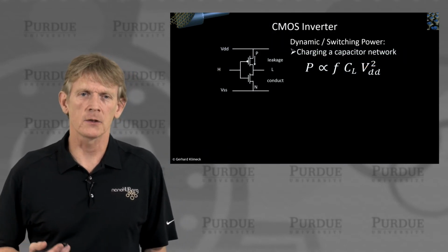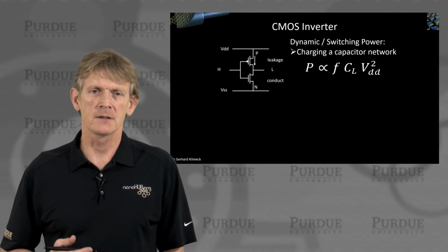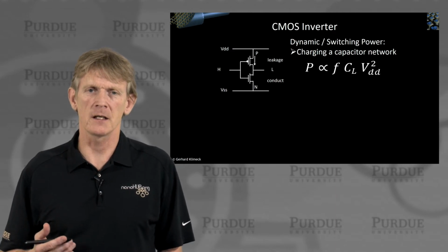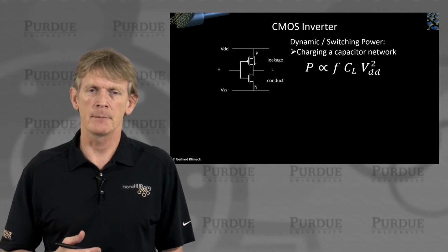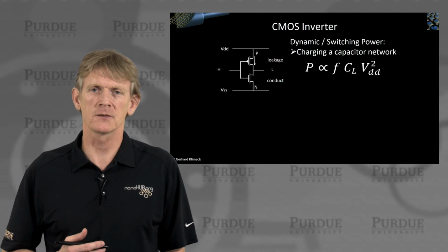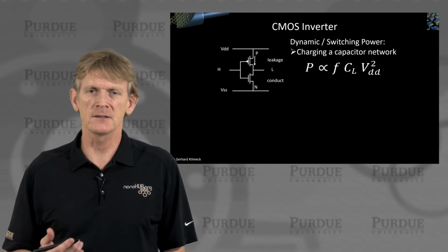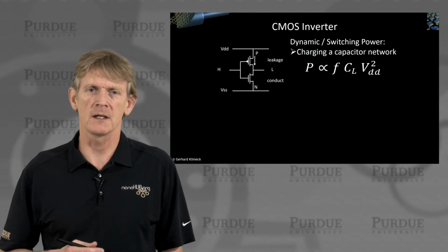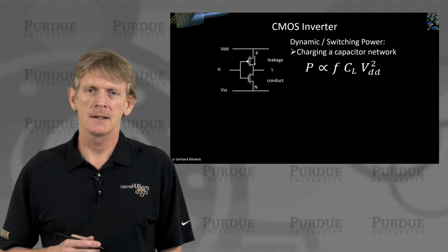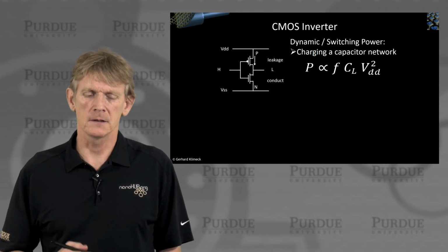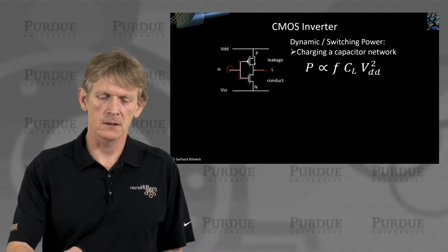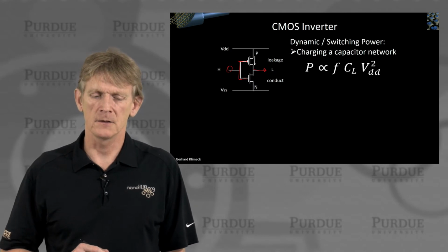What is the basic circuit element that really operates a chip? It's an inverter. It's basically holding the state of 1 and the state of 0 and pipelines that through some computation. And we haven't touched circuits much in this course at all. You might recognize these two symbols. There's an NMOS and a PMOS device, and they're set in series to each other. You can have a signal here on this shared line that might be high, that triggers this to be set to low, and vice versa.